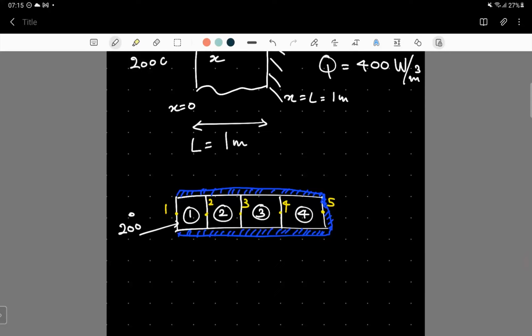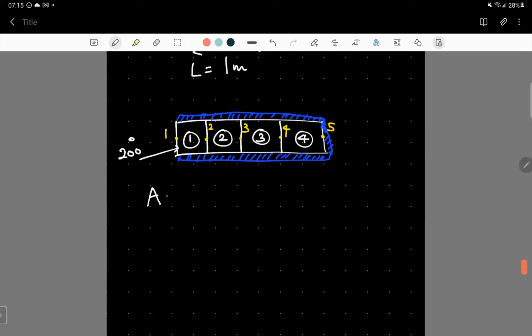We have already shown the discretized finite element model. So in order to make our life easier, let's consider 4 equal lengths of the elements having a unit cross-sectional area, that is, the area of this cross-section we assumed to be 1 square meter. A unit cross-section represents a typical cross-section of the wall, so it is representative. The perimeter of the wall is then insulated to obtain the correct boundary conditions. We can follow the same procedure as we did in the previous case.